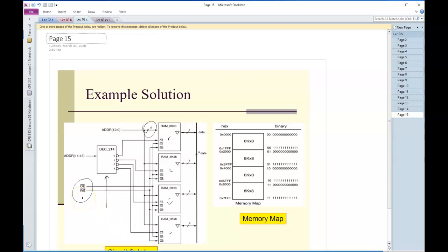That means the control signals for this 2 to 4 decoder effectively become the 2 most significant address bits. In this case, it's 13 and 14, which is essentially bits 14 and 15 in the word here. You can see it over here once again. There are 4 sets of bunches of 1s and bunches of 0s. These are equivalent. The difference is this row right here, which is effectively assigned by the decoder output right there. Looks good. And that's how I'm going to make larger memories from smaller ones.